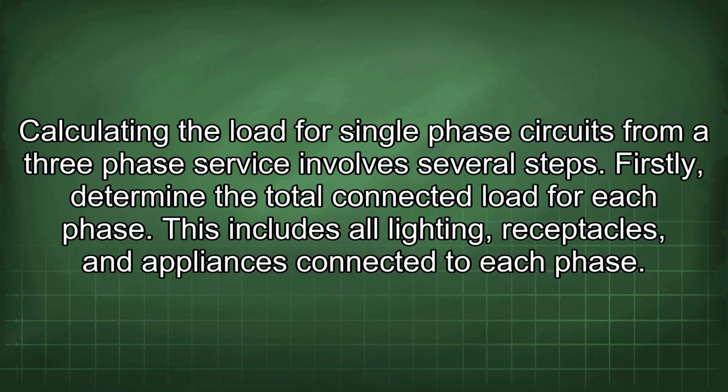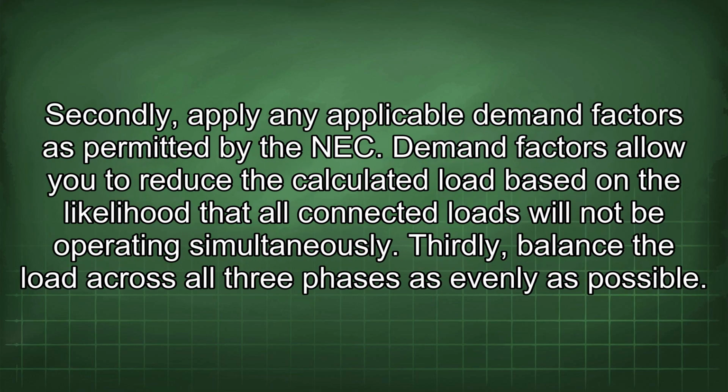Calculating the load for single-phase circuits from a three-phase service involves several steps. Firstly, determine the total connected load for each phase. This includes all lighting, receptacles, and appliances connected to each phase. Secondly, apply any applicable demand factors as permitted by the NEC.